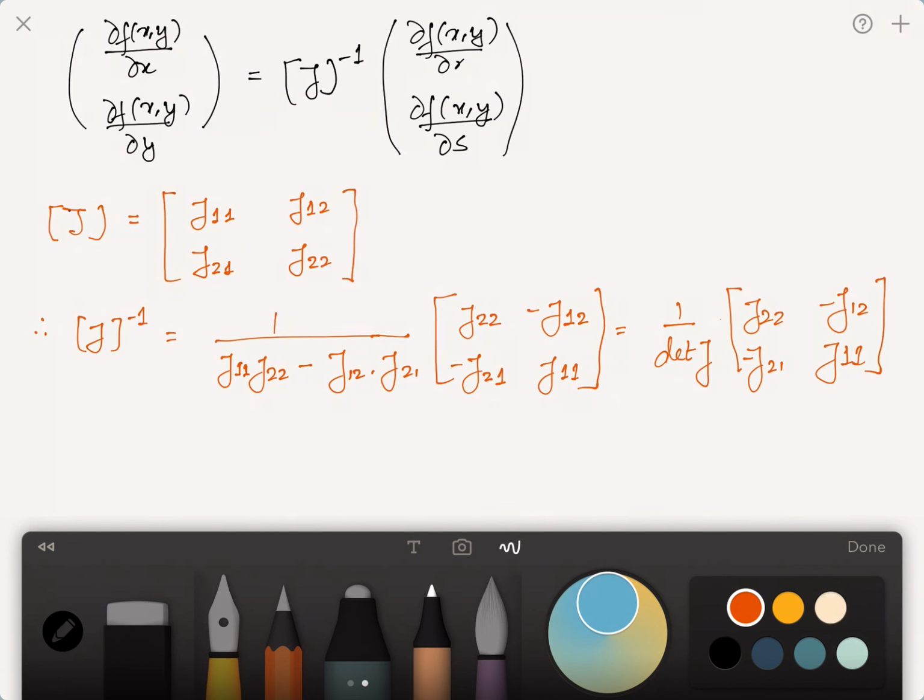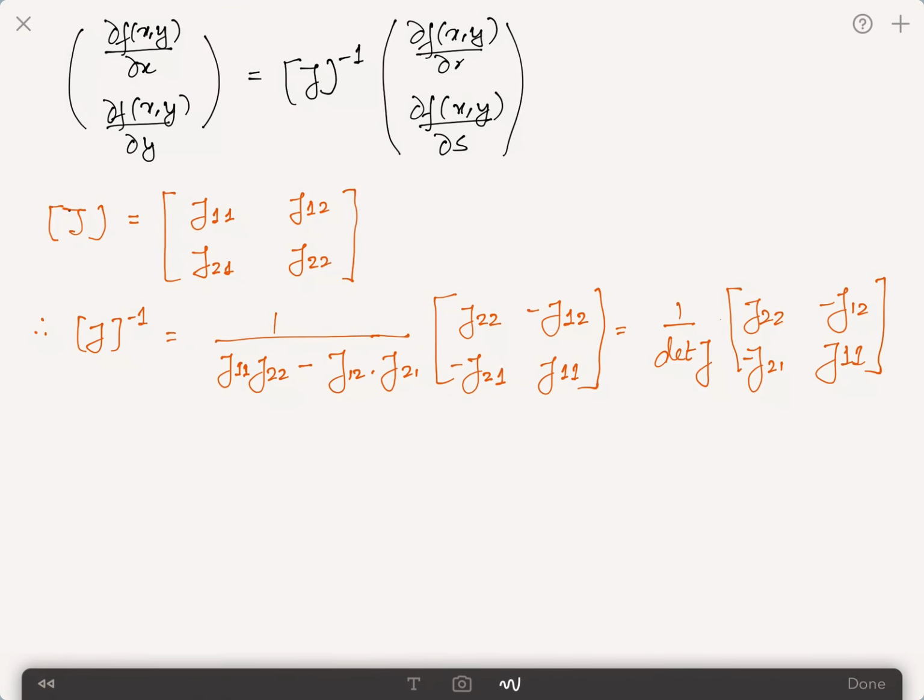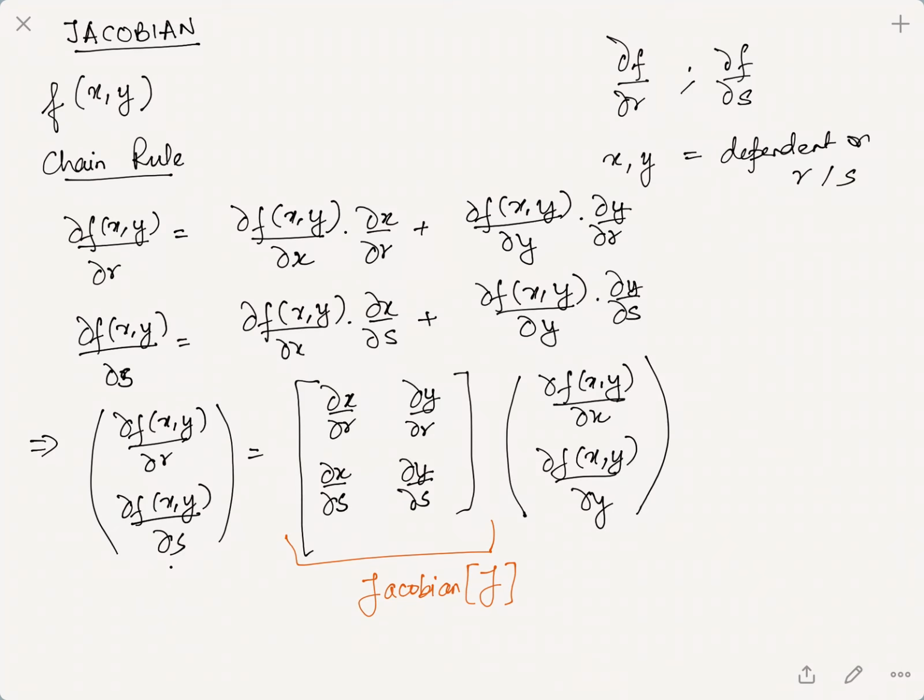However, you still need to understand that this transformation needed to be made. The Jacobian can therefore be evaluated for any given quadrilateral element by substituting the definition of x and y from the equation that we had proposed using the shape functions into the Jacobian matrix J. And as you can see very clearly from the previous slide, that is just a derivative of x and y with respect to r and s. And x and y are written in terms of the shape functions, which are therefore written in terms of r and s in the natural coordinates. So that's quite easy to calculate.